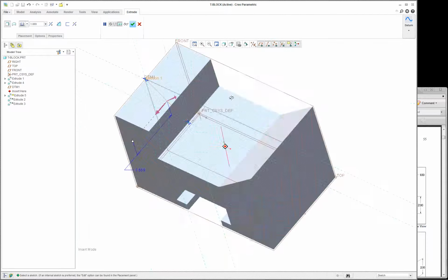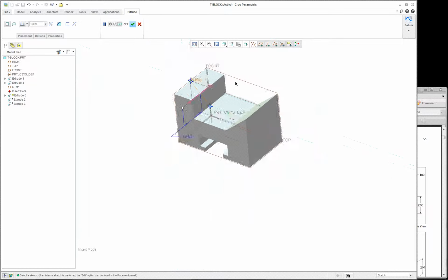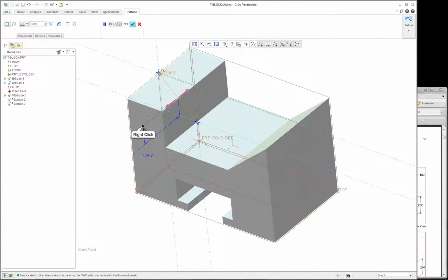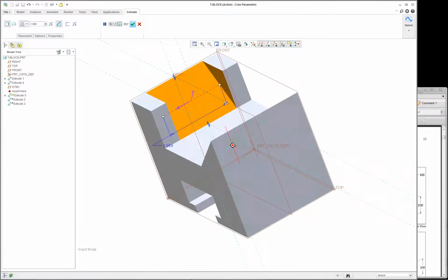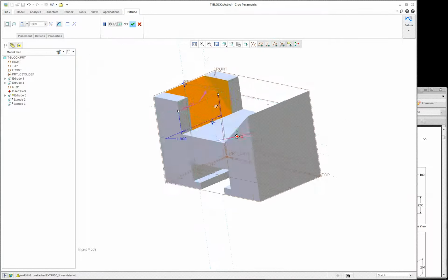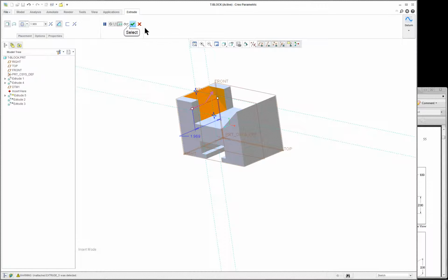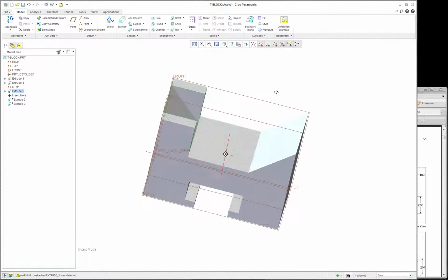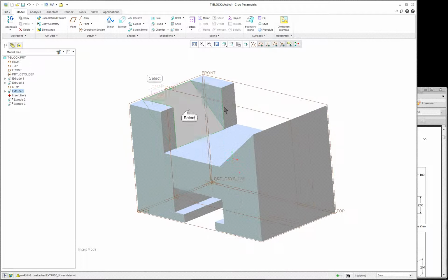And this is important. Which way do you want to cut? We want to have a symmetric cut. And I forgot to click on remove material, so you can see wherever you want the material removed. And of course, watch which way the arrows are pointing. Pointing in the wrong direction, they're going to fail. Feature will fail. And there's our cut. And I didn't give it a specific size, but I could double click on it.